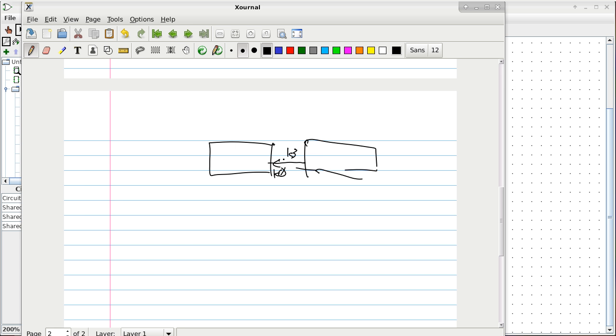So we still have dependency now, but it's not quite as bad as the typical carry ripple method. Because what we usually do in this case is you have a 32-bit adder here and a 32-bit adder here to make a 64-bit adder. It's nice that way because if you look at the 64-bit adder, K64 is a mess compared to K32. So it's less expensive to implement 2 32-bit adders and chain them like this. But what you lose is time. So sometimes it's a trade-off that manufacturers are willing to make.